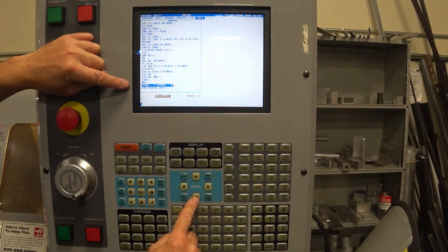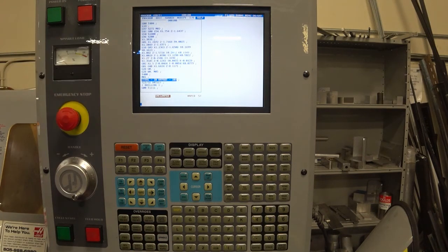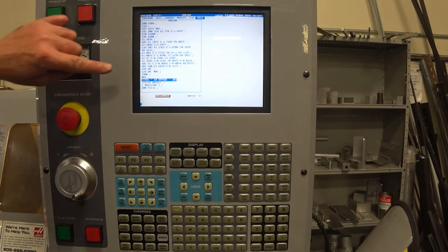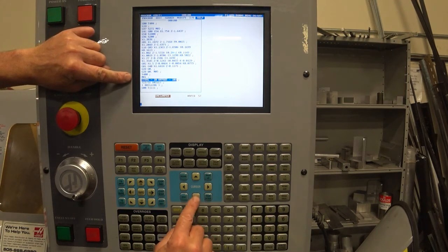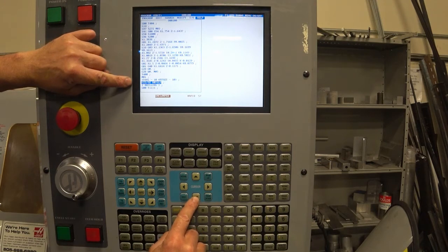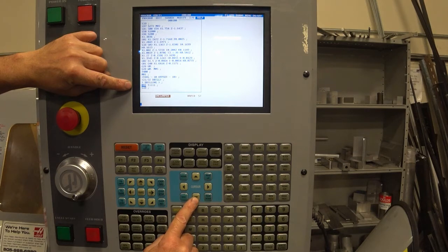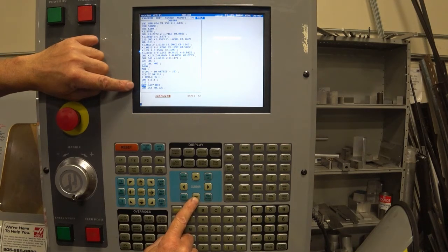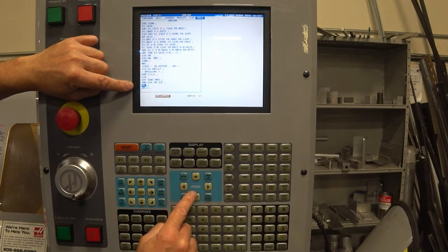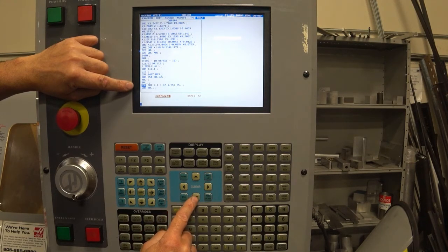Here we have more operator comments for a tool change. This is a drilling cycle, so you'll see that the feed method and surface control is different. Calling a tool T1111. Notice now G97 S487. This is fixed RPM at a 487 RPM speed rate. This RPM will not change throughout the preceding tool path. Along with this, you'll note that the feed rate will be denoted as F5.0. This is 5 inches a minute.